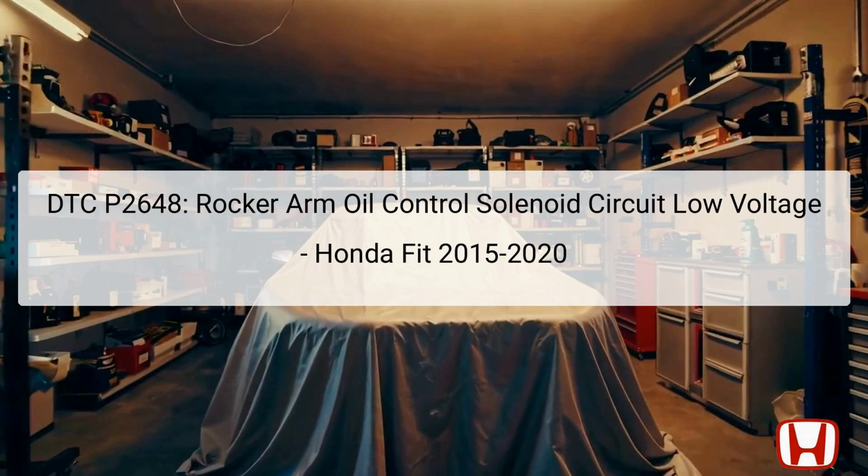This solenoid, located near the engine cylinder head, helps optimize engine performance by adjusting valve timing based on engine load and speed. When a low voltage condition is detected, it may lead to suboptimal engine performance, increased emissions, and potential engine damage if not addressed. This diagnostic trouble code utilizes the Honda Diagnostic System (HDS) for checks and validations. Troubleshooting should begin with verifying the presence of this DTC and following a systematic approach to address all underlying conditions.